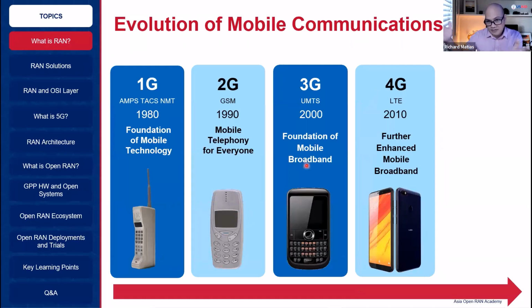For 3G it becomes 5 megahertz. And then for 4G it goes to 20 megahertz. And then after 20 megahertz, there's an improvement that we call carrier aggregation. So you can add more carriers from different frequencies to have a wider bandwidth for the transmission.